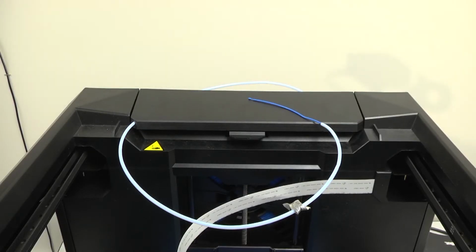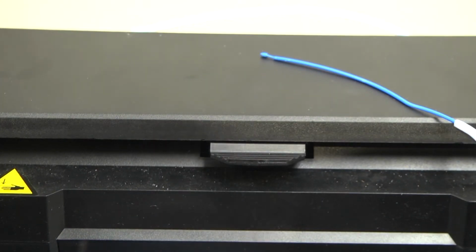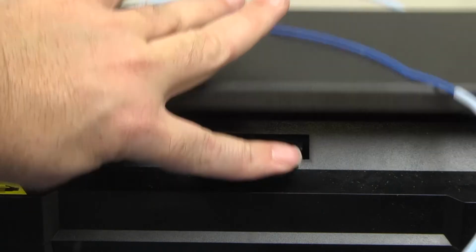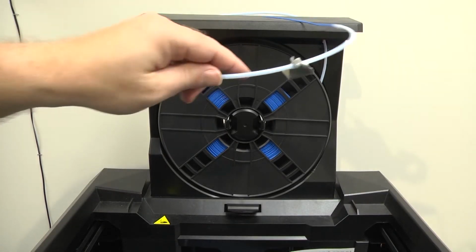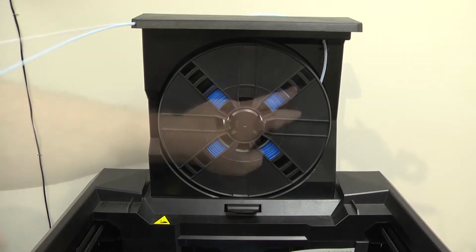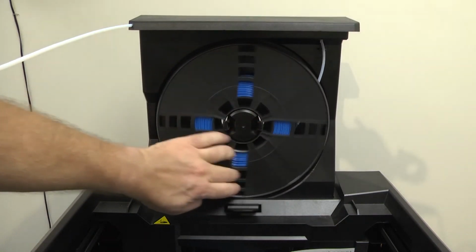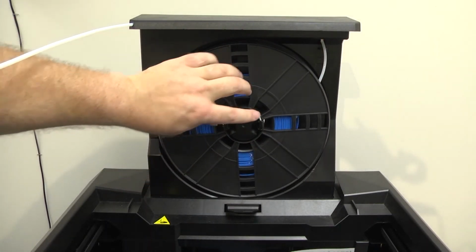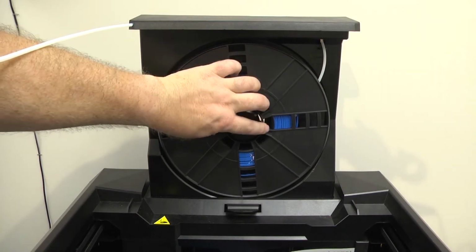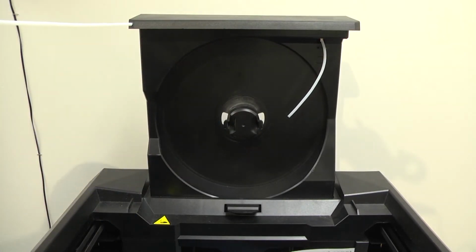The filament spool is in the back of the unit. To access this, you must push down on the lever and pull up. The unit will lock into place. Turn the filament clockwise to remove the old filament. You must completely empty the filament straw. Then squeeze the release catch in and pull the filament from the unit.